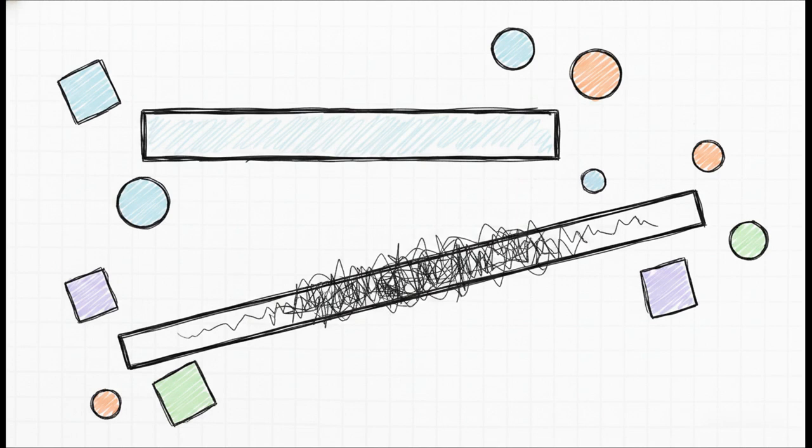But hey, it's not just the metal traces. A huge, often hidden culprit here is via resistance. When you drop down from metal 4 to metal 1, you aren't just making a simple connection. You're actually forcing current through a super narrow, highly resistive tungsten plug. This is exactly why experienced layout engineers will drop via arrays, basically a grid of multiple vias, instead of just relying on a single one. It cuts that resistance down in parallel. And you're going to see this exact same effect with poly, diffusion, and contact resistance all over your layout.